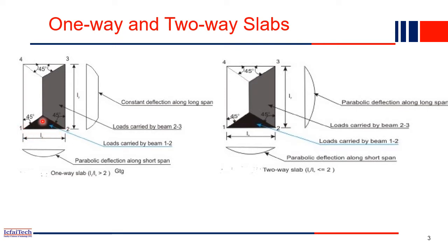About the x-axis, if you see at the center of the beam, basically the deformation is maximum. This is the deformation shape you will get, because here the load is maximum, which means the deformation will also be maximum. Similarly, here the load is less, so the deformation is also less. So this is the typical deformation about the x-axis, and this is a typical deformation about the y-axis.